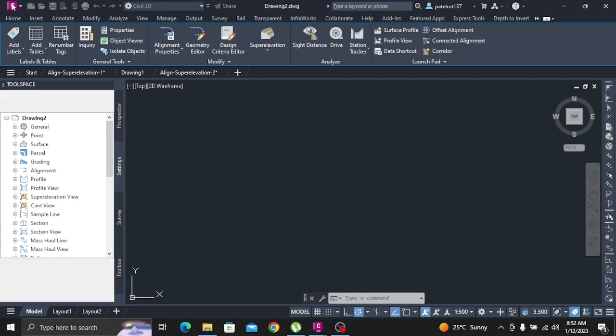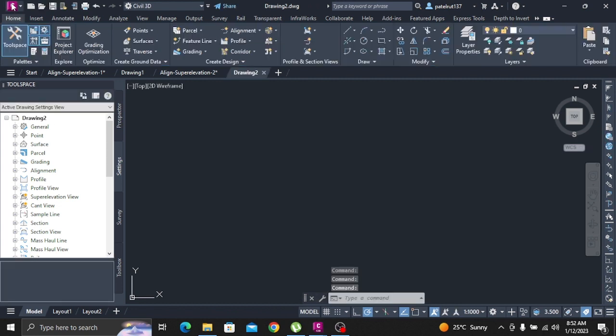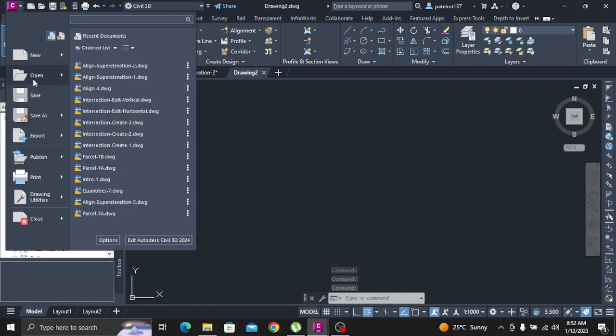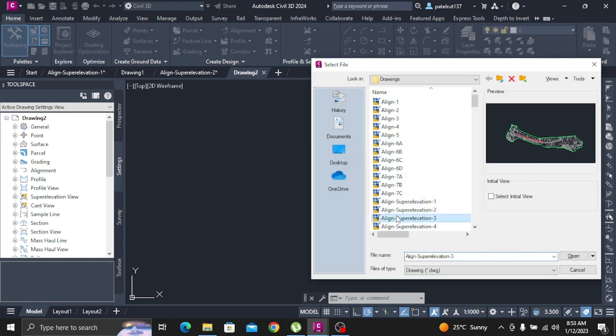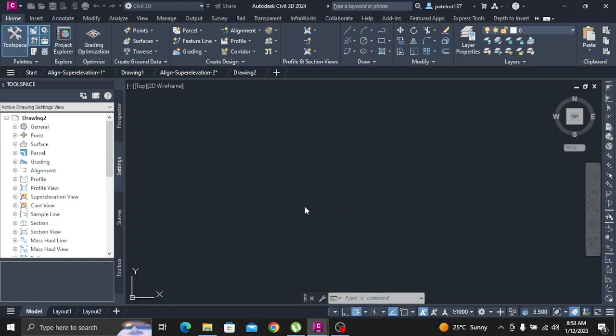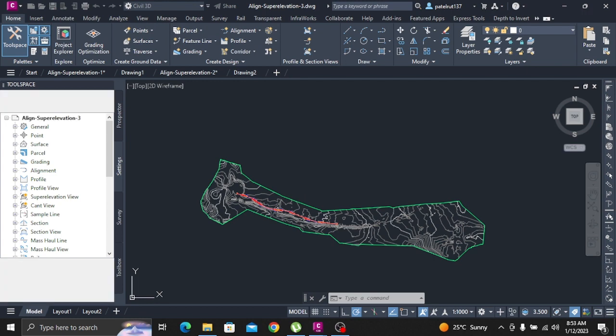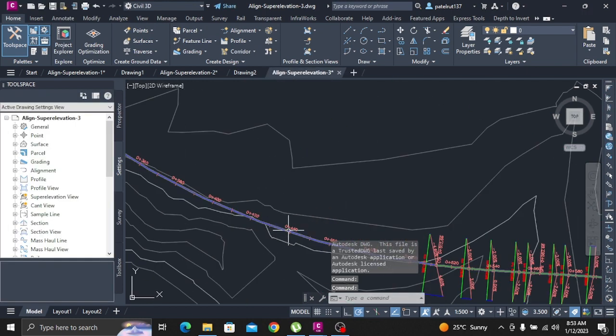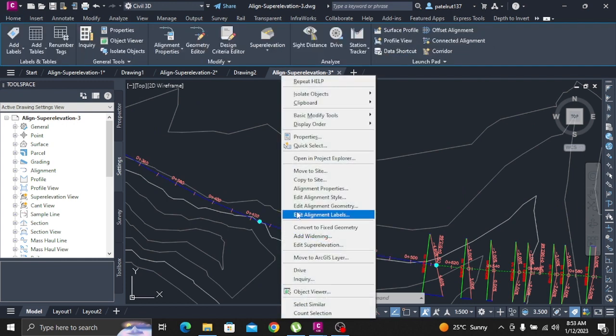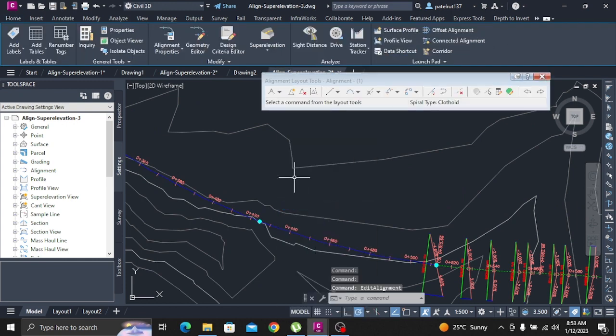On the command line, enter 568. Press Enter. A new manual station, which starts at station 0+568.00, is displayed in the Superelevation Tabular Editor. Right-click the manual station. Click Assign Critical Station End Normal Shoulder.